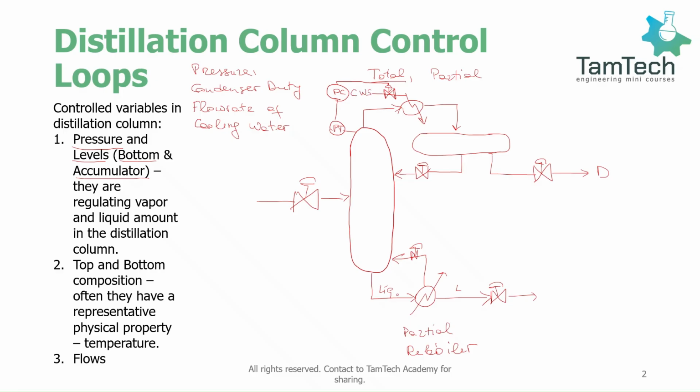And of course, at the end, we also have a cooling water return line too, but it is not our interest. So how we control, the philosophy is like that. Imagine we increase our cooling supply to our condenser. So the more cooling water that we have, the more vapor that enters our total condenser will be condensed to liquid.